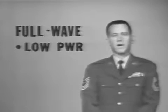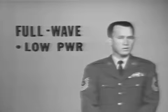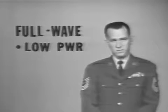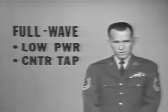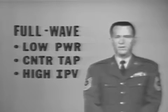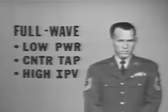Even the full-wave rectifier has its limitations. Though able to supply more current to the external circuit than the half-wave, it is still a relatively low-power device. And because it requires a center-tap transformer, only half the available secondary voltage is felt in the output. Another limitation of the full-wave rectifier is the peak inverse voltage applied to each non-conducting diode.